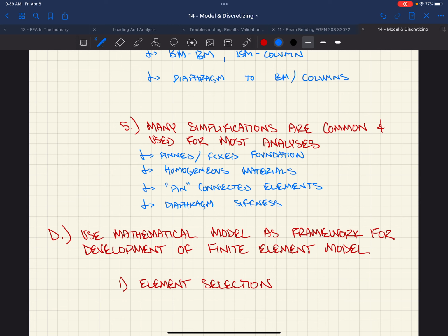But I agree. Sheathing gap, I mean, when you're doing your diaphragms, don't you tell them that they need to do something like this? They stagger it, which gives you more shear value for the diaphragms, for those of you in wood. We always assume they orient them the worst way, and so I think the worst value is possible because you never know, right?